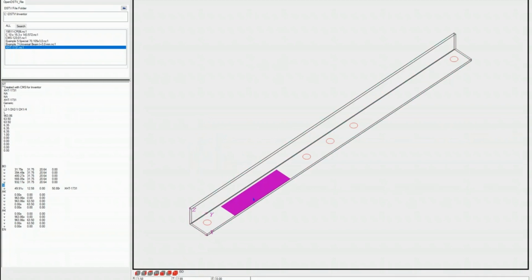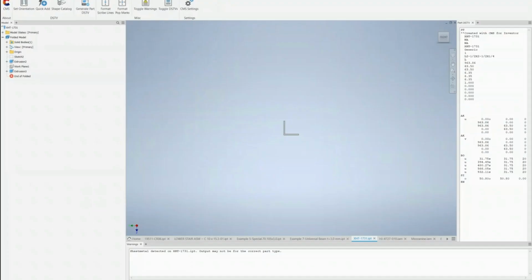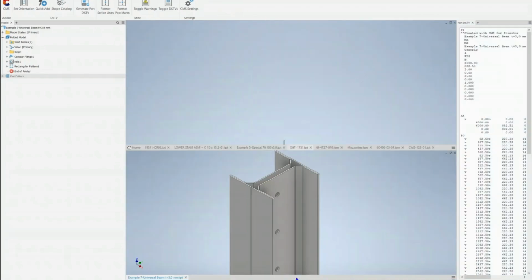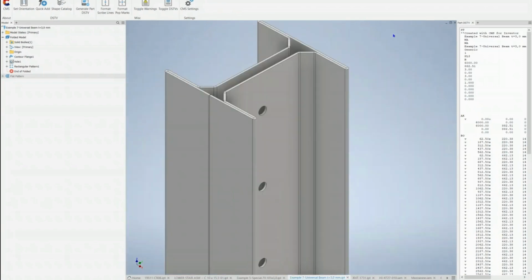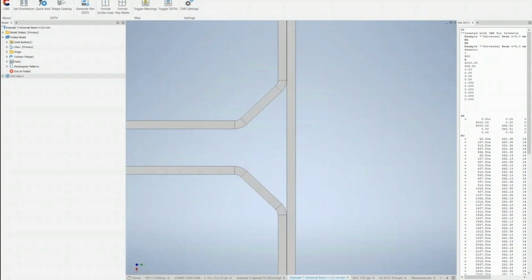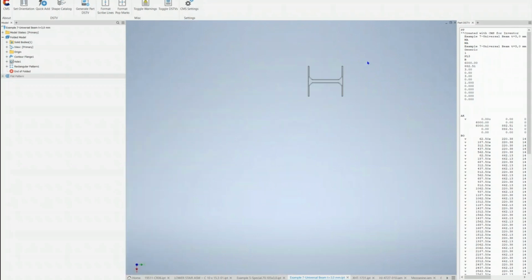So you see that you have that sheet metal thing created as an angle, and we were able to create an NC1 file for an angle as well. If I go back to the previous example here, and try to create an NC1 file for this one, treating it as a beam, I'm losing the term, as a UB beam, which is an I beam, all I need to do is put it like an I.